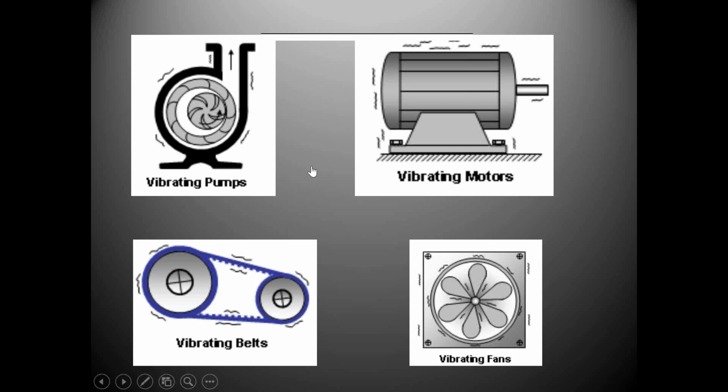In the lower left-hand corner, if you have a fan that has 6 blades on it, when I put my vibration meter on there, I'm going to see a spike at 6 times RPM. Sometimes an electric motor, depending on how many rotors there are in the motor, you might see those spikes at that many times RPM. So again, it's understanding what is the natural frequency, what's that natural vibration that's going to come off of those units, or what am I going to see in my vibration report? Well, a lot of times it's knowing how your equipment's built and what the components in the equipment are.